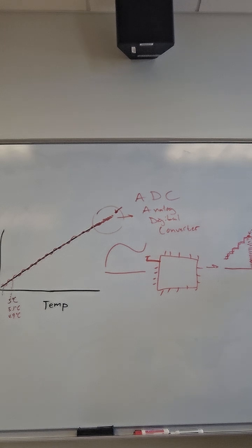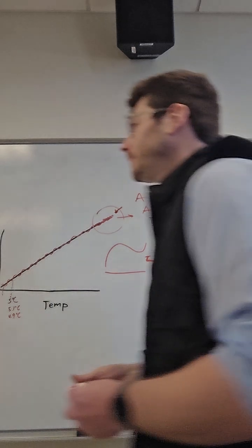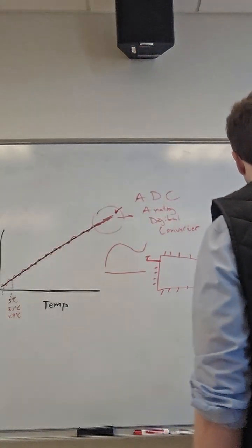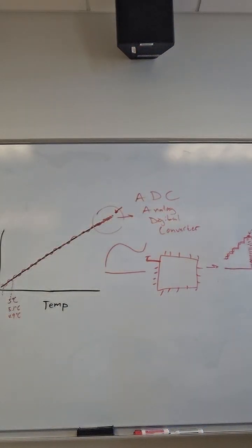And then each time slice over time, we say, hey, sensor, do an instant digitization. What is the voltage on this pin now? And boom, it goes, it is in bin 2 out of 100. It goes, okay, thank you, that's in bin 2 out of 100. One more loop, okay, what is the voltage now? And then it's, oh, we've raised one, it's now 3 over 100. And then we just keep doing that, acting on the feedback, and proceeding accordingly. So this still gets us some unitless number.